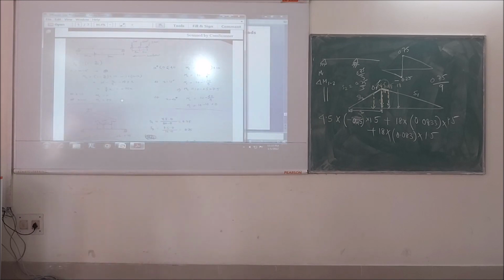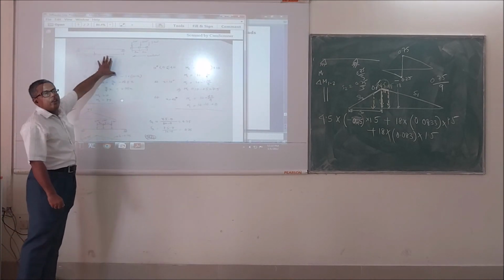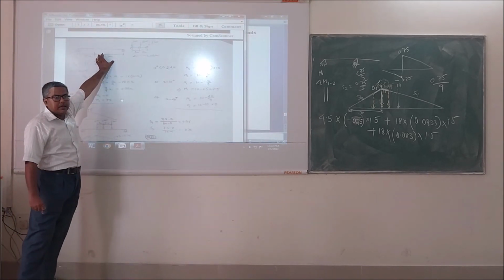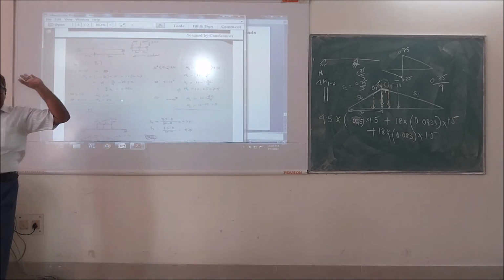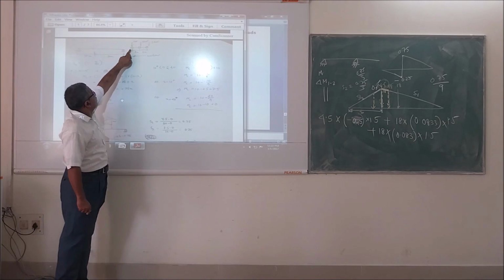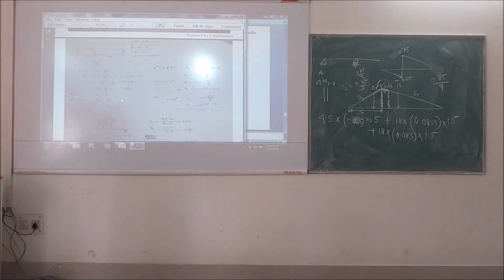So you see here this is point C. The beam, the girder, is 40 meter length. This side is 10 meter, this side is 30 meter. Now you will have to find out the maximum influence because of this 2 kilonewton, 4 kilonewton, 3 kilonewton load. There is a small difference from the previous load case.